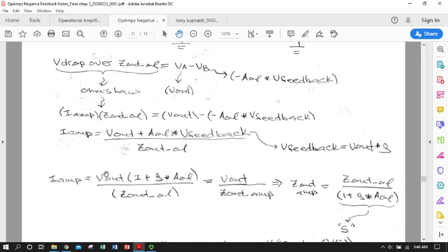We've got voltage, current, and we know that V equals IR, and here's our I, here's our V. And so if we imagine everything else here being 1 over R, in this case it's 1 over Z output contribution from the amplifier in the closed loop configuration, but basically think of it as an R. You can write everything here as 1 over Z out amplifier. Okay, so we just applied Ohm's law again.